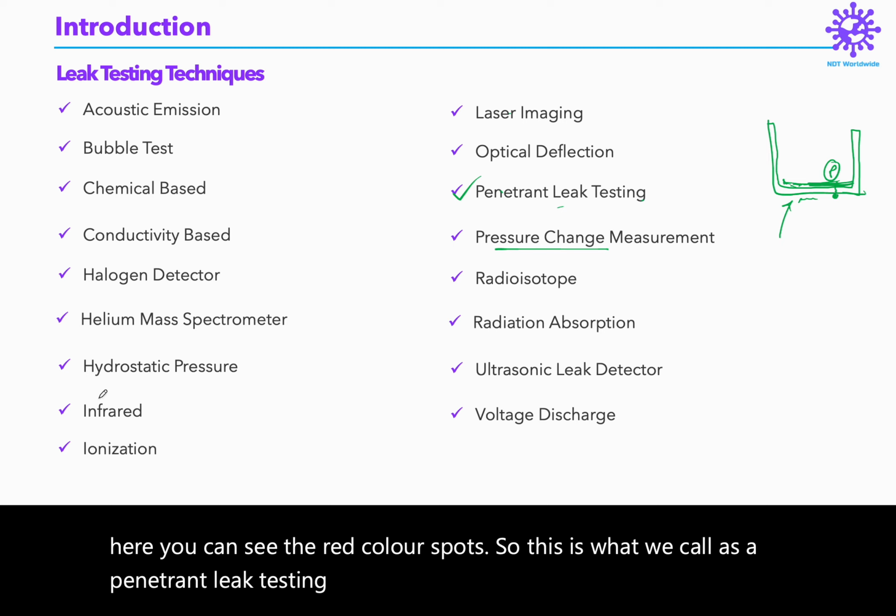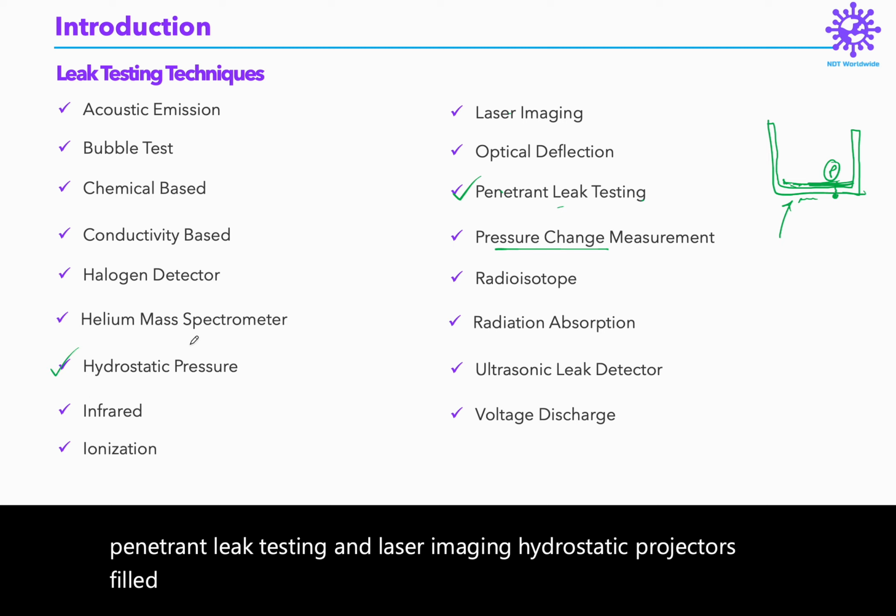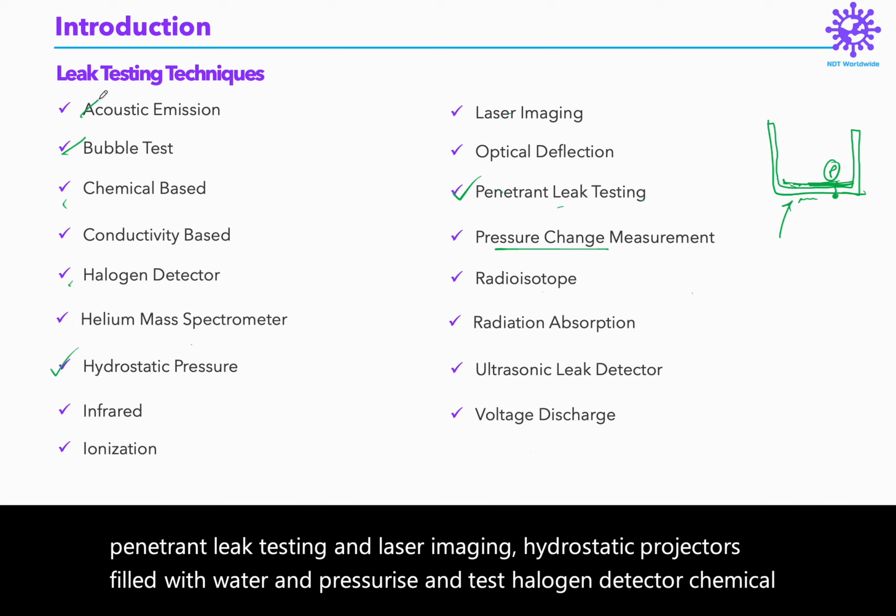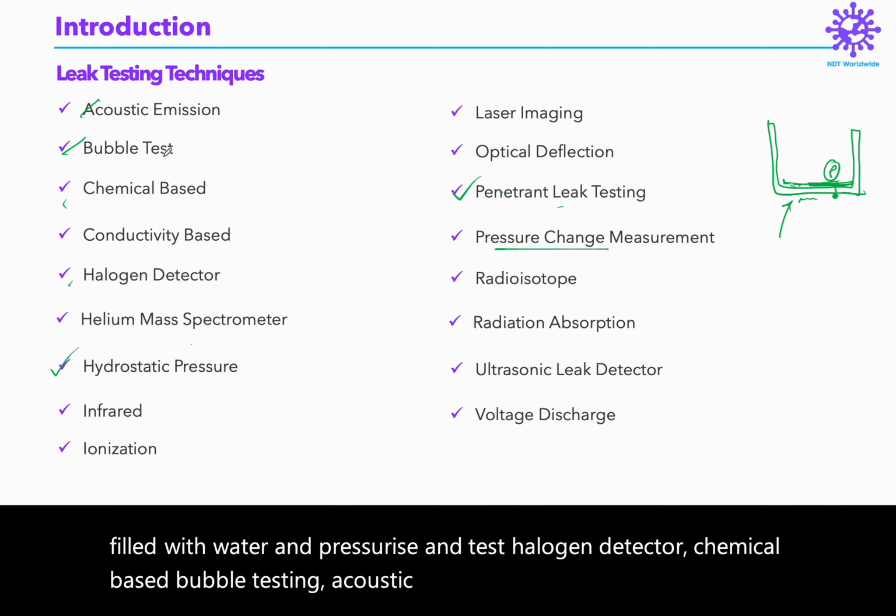And laser imaging, hydrostatic pressure test, fill with water and pressurize and test. Halogen detector, chemical based, bubble leak testing, acoustic emission. These are all some of the popular techniques.